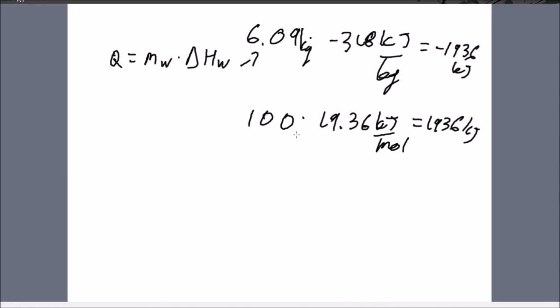And the last question is just pure theory. Over a period of time, what would happen if the heat exchange membrane became dirty and less efficient? Well, what's the purpose of our experiment? We wanted to increase the temperature of propane. So if it's less good at heating it, the propane is going to be cooler, and that means the water is going to be hotter, because it's not going to give off as much heat as we would like it to. That's all it is.